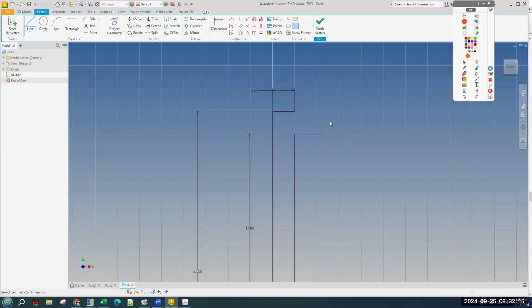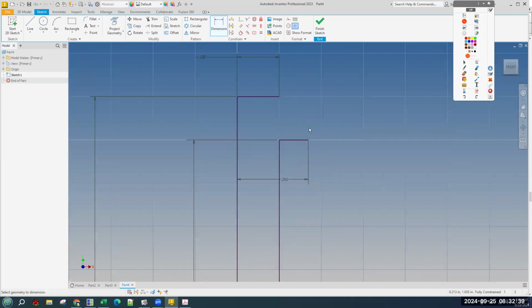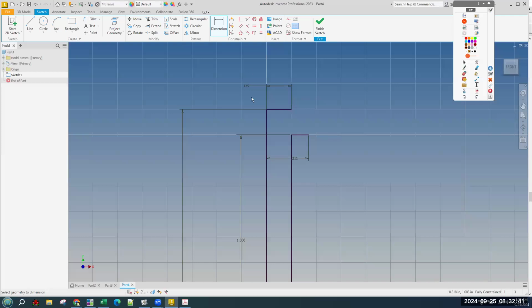And this is the same thing. The dimension that we are given is the size of the bolt or the peg all the way across. And this dimension needs to be 0.422. So the distance we're interested in is from the end point of this line to the center axis, and that needs to be 0.422/2. Okay, horizontal dimensions are always halved because the part feature doubles them, so there's that.